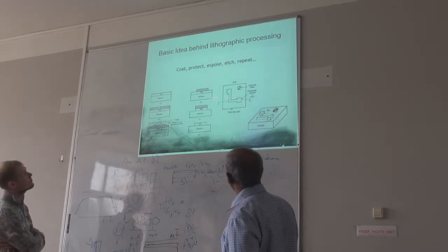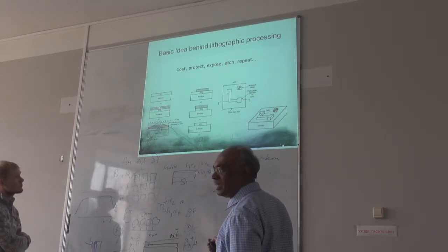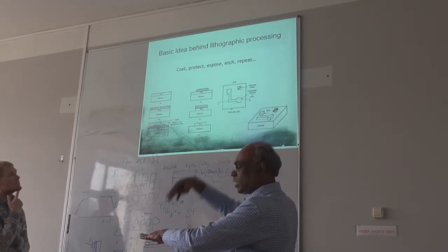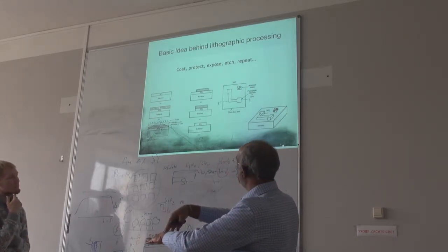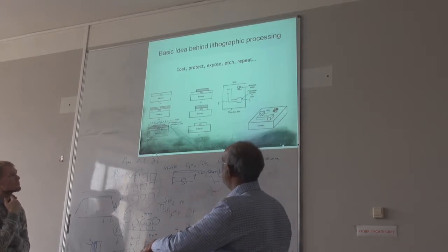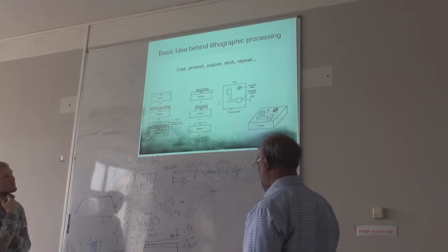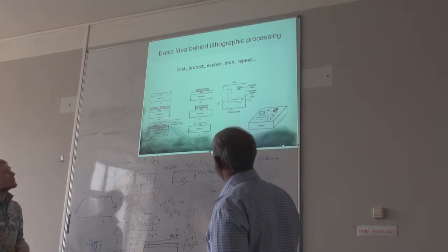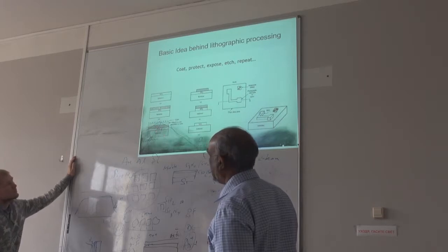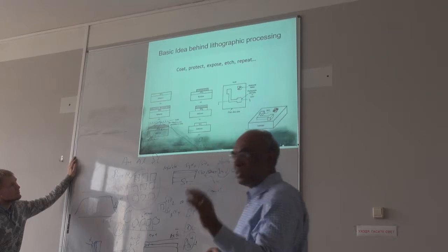Now you take this mask and put it here. You just put it here. That has that pattern. In photolithography, we just expose to light. If you use UV light, then this part is exposed to that light, but not this part. Only this is the hole here.